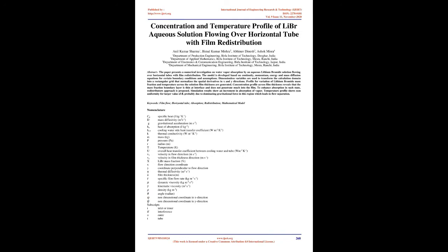Concentration profile across film thickness reveals that the mass fraction boundary layer is thin at the interface and does not penetrate much into the film. To enhance absorption in such a state, a redistributor approach is proposed. Simulation results show an increment in absorption of vapor.